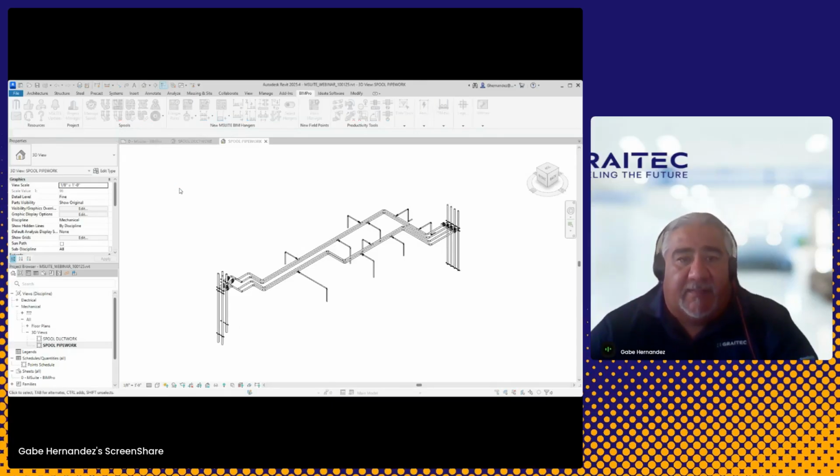So when I select on it, you get some options here, which are very cool. Let me move these out. Let me stretch it out. So you can do this by service, right? So I can do one at a time. And then I have my naming conventions that I can choose here. Spool length, minimums and maximums, pipe diameter minimums and maximums. I've got direction, max length after direction. I can do break at flanges, spool olets, valves, and equipment. And then I have spool weight maximums and elevation maximums as well.